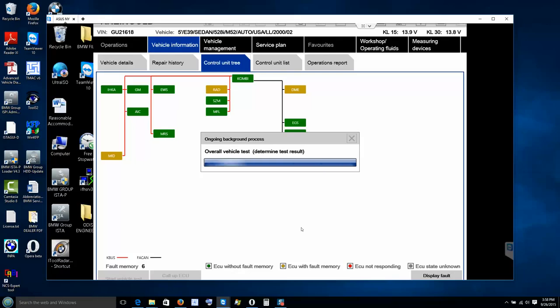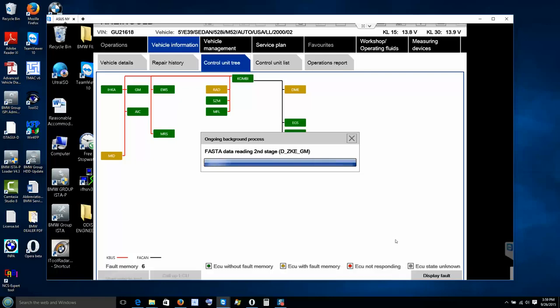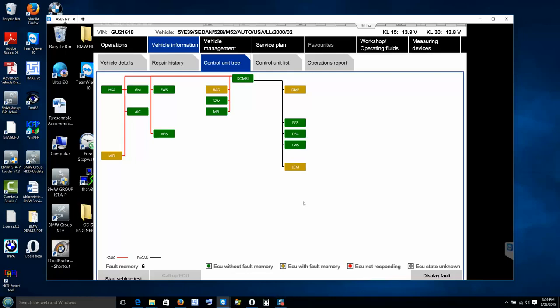Yeah, simple. We can create a test plan for that too and look at how to fix it. It has to be other things causing it, you know what I mean? Like the rear, they changed and put aftermarket lights on the car, and the rear lights and the instrument cluster is on, showing you that the bulbs are blown. It's a driver footwell module, I think the FRM is responsible for that. I know the aftermarket people used to sell a little resistor that you put on the back of those lights.